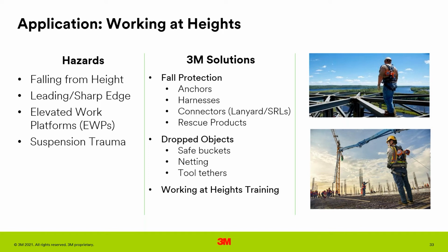Also, you have people working in elevated work platforms. You definitely don't want to fall out of these. There have been lots of accidents where people are ejected from these elevated work platforms. So personal SRLs are great for these elevated work platforms.